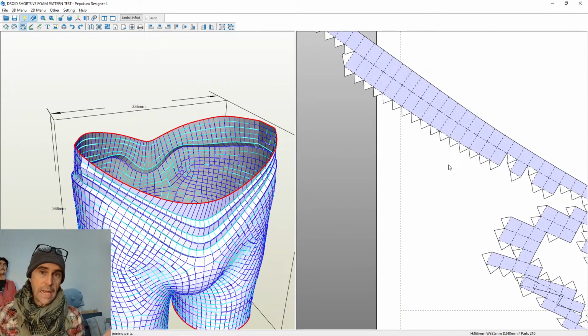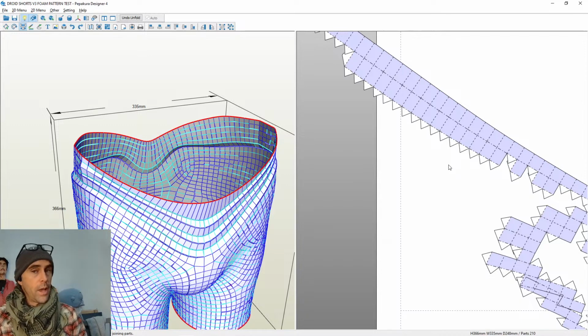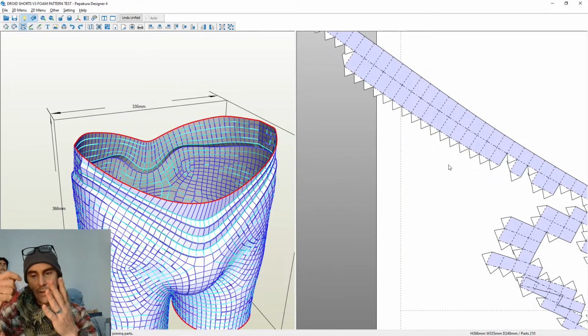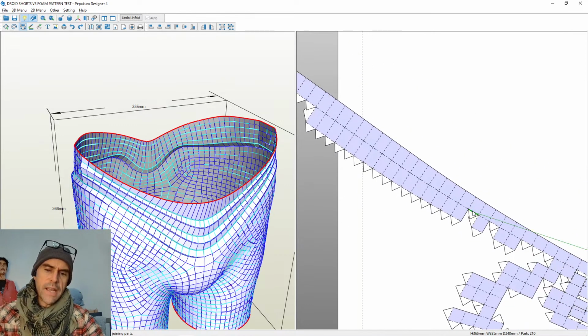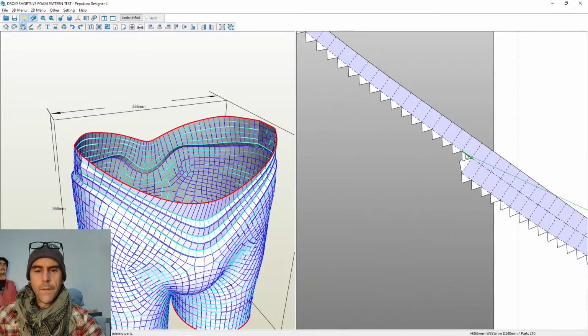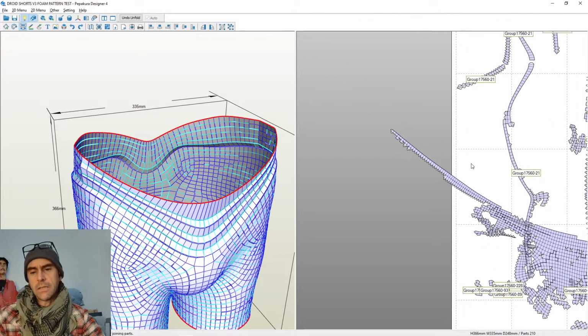What's really cool about that is you can pre-coat the pieces with the glue and let it completely dry. Especially if you're working on set and need some pre-coated pieces for reinforcement, you can pre-coat them, let it dry, and then just have a little acetone in a little bottle, quick brush it on, and it reactivates the glue. Then you can stick it together, and it's really, really strong.